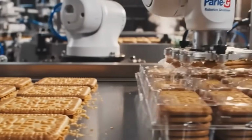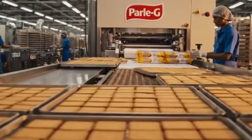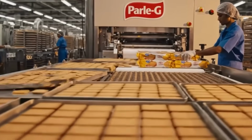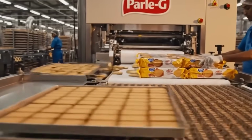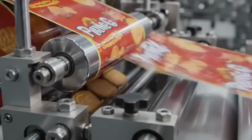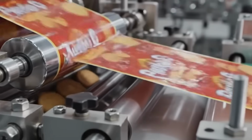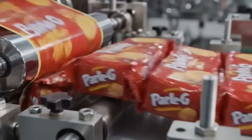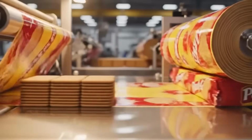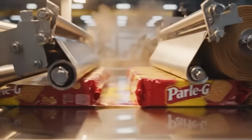Packaging is designed to protect biscuits from moisture and breakage. Biscuits are collated into stacks and oriented. Stacking systems use lanes and pushers to form uniform packs. The packs are then flow wrapped or placed into trays. Flow wrapping uses barrier film that blocks water vapor. Tray packs provide mechanical support and reduce breakage during transport.